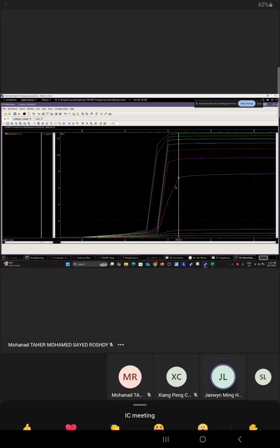By the way, we just changed only one of the NMOS, not the tail as well. If we increase the NMOS width, we are indirectly increasing the tail current for the second stage. Then the ceiling actually decreases.